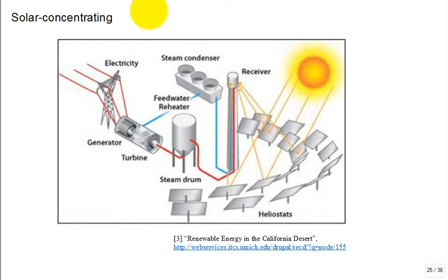Solar concentrating power. Here, forget the organic Rankine cycle. If you put these heliostats out in the field, which you've probably seen pictures of, and they are oriented such that they all reflect to a receiver, the receiver then really gets pounded. And you may put a liquid metal in there to really absorb that heat. And then bring that liquid metal through a piping system into another heat exchanger or steam drum or something, and maybe you do the loop for the liquid metal. It's not shown here up to the receiver. Or maybe you bring the water all the way to the receiver and just beat it up. It's going to be hot, hot, hot coming out. Pass it through the turbine, make electricity, have to reject heat. If you're in the desert where they like to put these, usually you air cool, so you're not having to supply makeup water. If you're in Texas, you have a lake, and you let some of the water just evaporate off the lake.